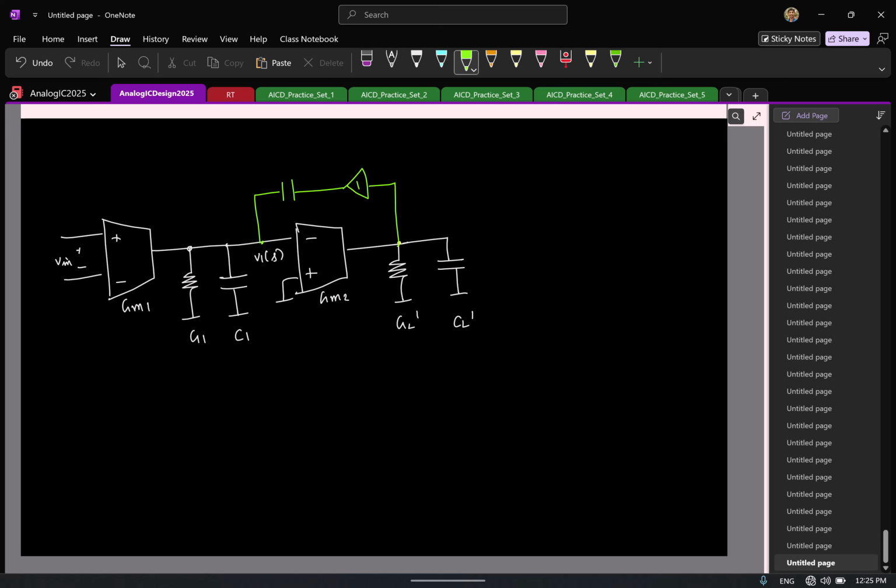So this way you have the feedback alone, but not feed forward. Now, of course, in practice you can't make an ideal buffer, so it will have its own output resistance. So the moment you have an output resistance for the buffer, things will be slightly different. I'll give it as a practice problem to work out where the zeros will be in this case. And of course, now the pole locations also slightly get changed. Let's not worry so much.